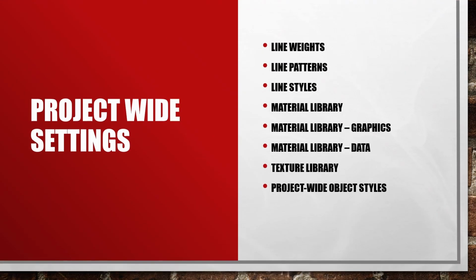Project-wide settings establish the default look and feel of the model. They are typically defined to match company or client AutoCAD or BIM standards. Any change here affects every view unless specifically overridden later. These settings should be tightly controlled within a BIM execution plan.